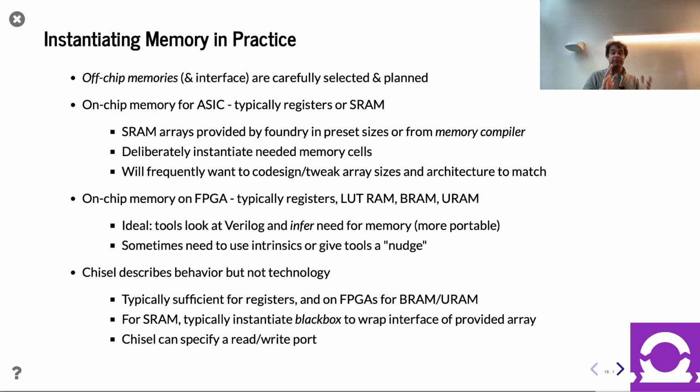So when it comes to memories, the methodologies typically let the tools infer the memories. Now, it's not foolproof, right? It's not guaranteed. But ideally, you write Verilog in a way where the tools can infer what memories are possible, and they'll make better choices about, given the kernelization of this design, you should use BRAM, you should use LUTRAM or registers. It'll make those choices for you.